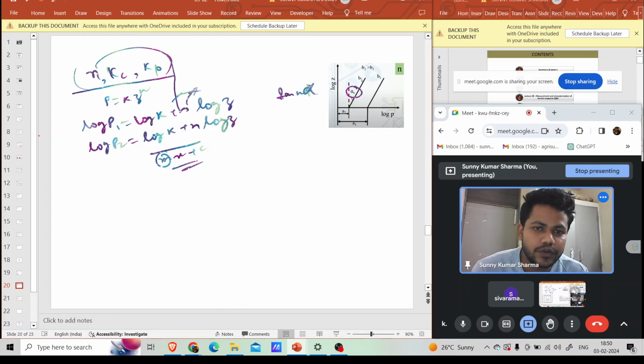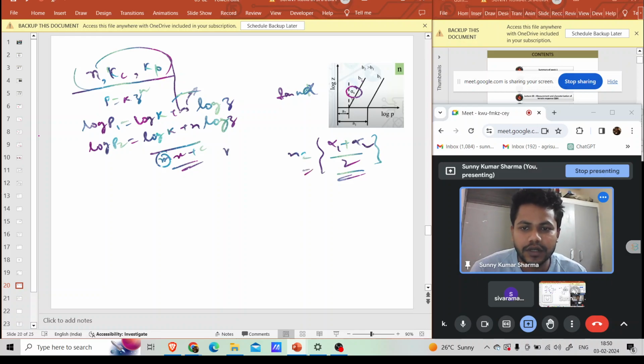And suppose the two curves are not parallel, they are at some different angles. Suppose you get alpha 1 and alpha 2, then the tan of (alpha 1 plus alpha 2) by 2 will be your exponent of sinkage. For Kc and Kphi, if you have only two plates, then you take z equal to 1, sinkage is 1, and this side will be 0, and the intercepts are A1 and A2 for the two plates.